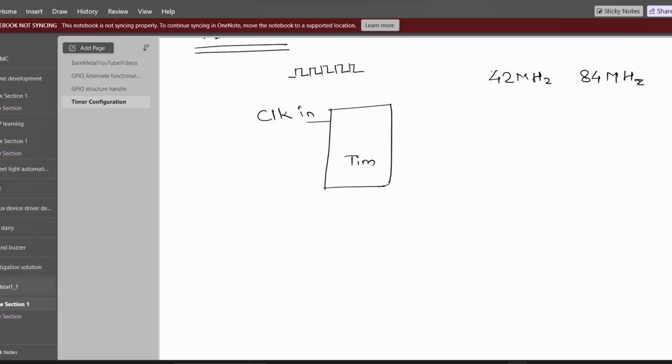If we invert 1 megahertz, we get one clock period of 1 microsecond, and obviously divided by 84 will be the period for this 84 megahertz. We don't want that fast a clock. If I calculate using this clock, it will be a huge headache to measure it continuously.